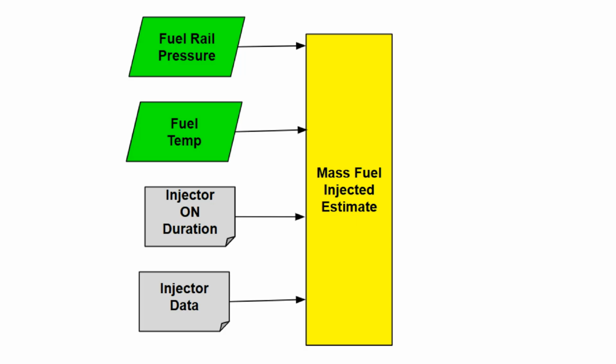Also, to simplify these videos, EGR is going to be ignored for now since it does somewhat complicate the exhaust temperature model. The other primary input to the exhaust temperature math model is the mass or weight of the fuel that is injected. The ECM must calculate the mass of fuel for each cylinder firing event, which is typically measured in units of milligrams per stroke. The ECM determines the mass of fuel to be injected to reach or to maintain the desired engine speed or governor reference speed.